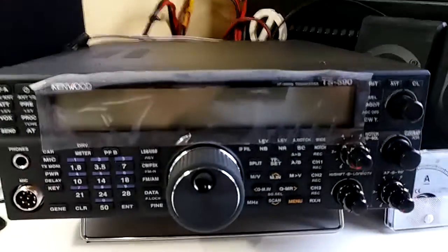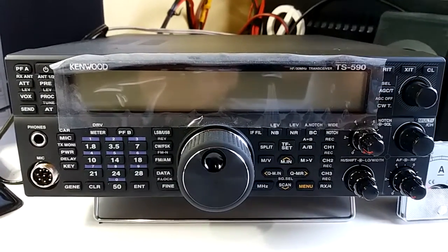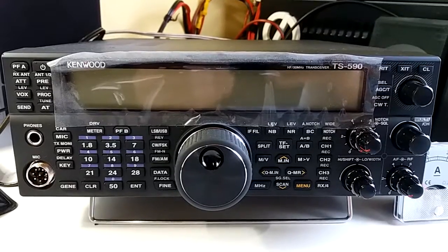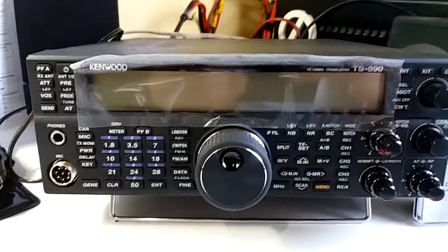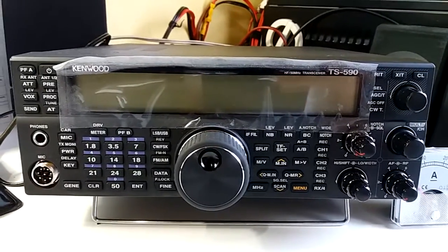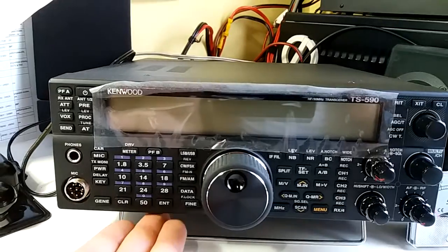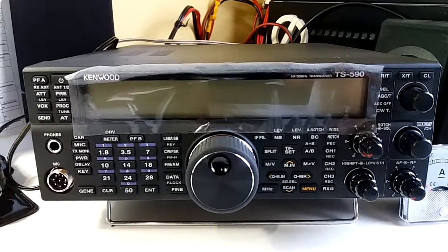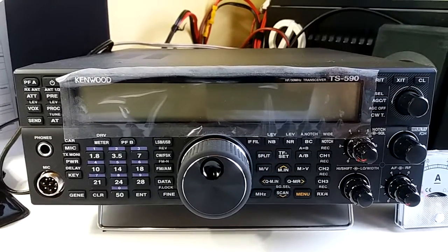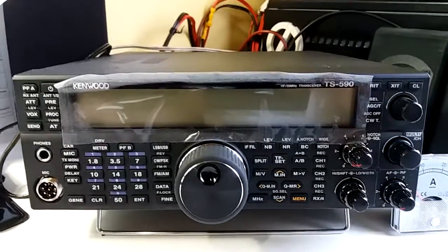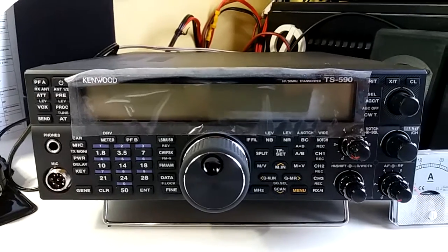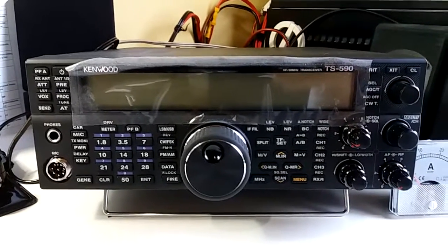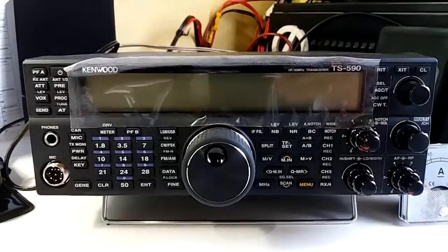I'm going to tune the 590SG to a world clock frequency at 10 megahertz, which is transmitting a constant CW tone. In a previous video I showed how to open the rear cover of this transceiver and, with the help of a screwdriver, tune the master oscillator to the exact frequency. I have done this, and now I'm wondering how much drift there is, or how stable the master oscillator is close to the 10 megahertz frequency that I calibrated in my previous video.